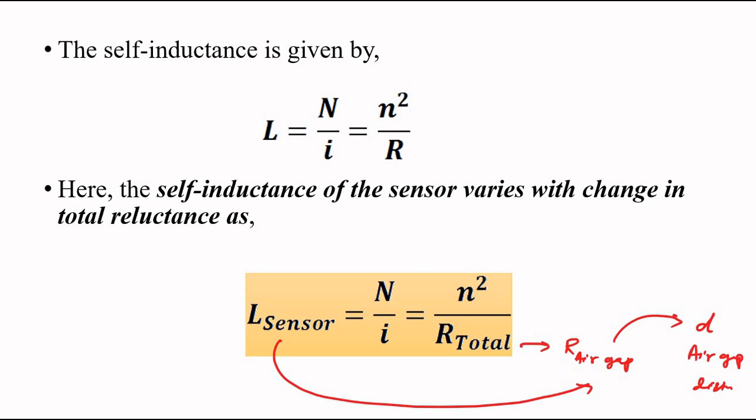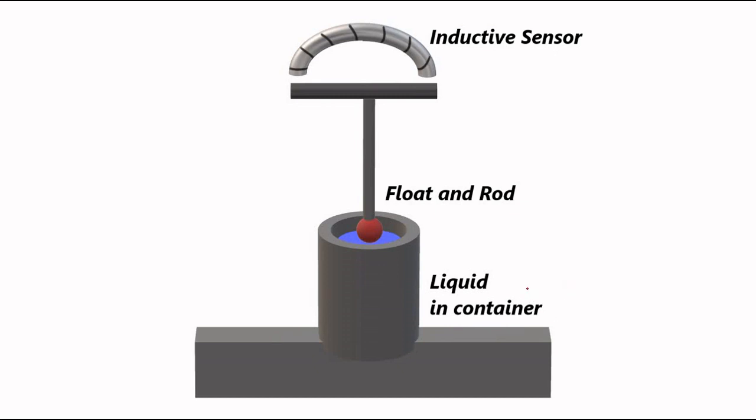First, we have the liquid in the container, and we have the Bourdon tube, which is connected to the source, the liquid column, and it measures the liquid column pressure. And the inductive sensor measures the height or level of the liquid. So it can be done in various ways. This is one arrangement. In another arrangement, what can be done?